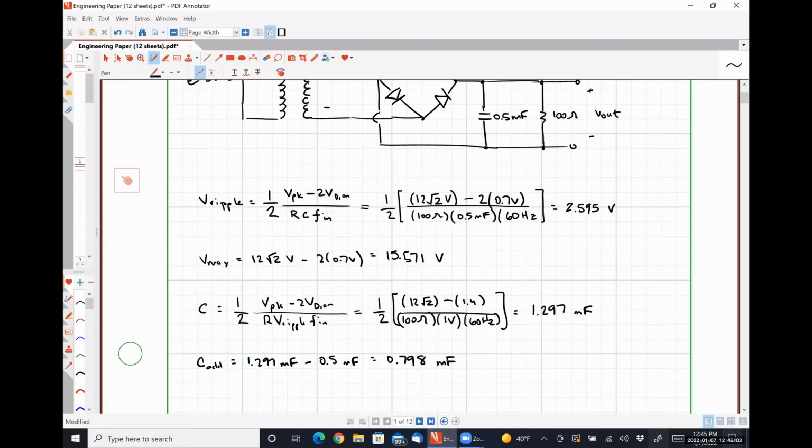Because we saw for a 10 volt input with plus or minus 10%, a variation of a fraction of a percent in the output voltage when we were defining and deriving our small signal model, right? So as long as we're not seeing that the ripple is effectively half of our output signal, we should probably be pretty good to slap a voltage regulator on it and call it a day.